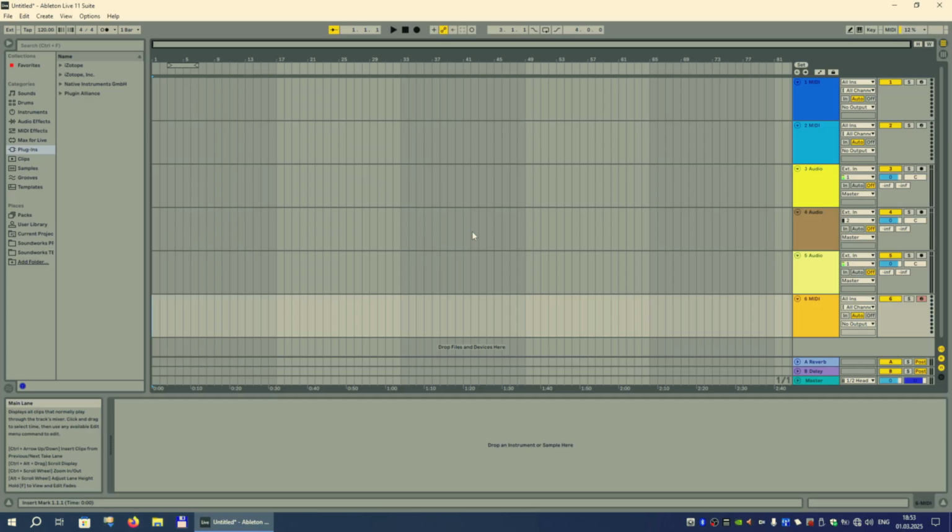Group tracks can only be used with audio and MIDI tracks. So basically you can take any number of audio and MIDI tracks in any combination and group them. You can even group them further into subgroups, but you cannot put a track in more than one group on the same grouping level. To make a group, you need to select required tracks, right-click on one of them and then click on Group Tracks.